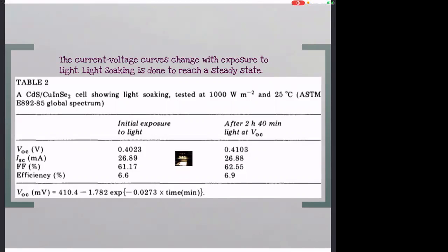In fact, I visited a factory based in California many years ago, and they have sections where they simply let the solar cells sit under very bright light like this for a long time, so it stabilizes and reaches a specific efficiency value. Otherwise, it's very hard to give a value to your customers. So this is part of the quality control protocol that people use.